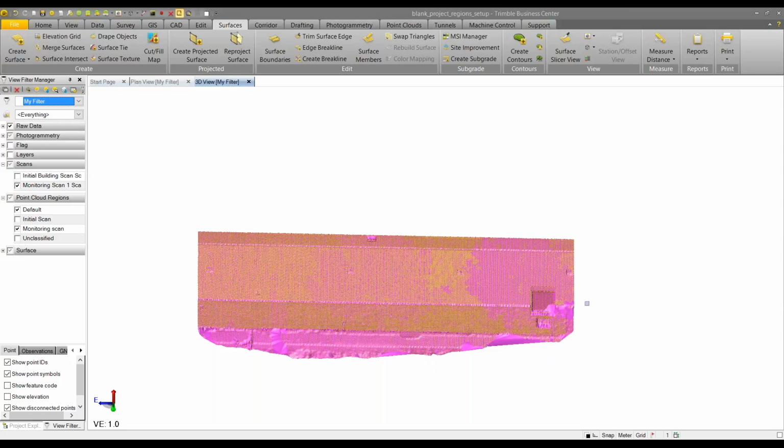So if I've heard you correctly, you're asking if you can use this to monitor cracks or just identify cracks? Yeah. Okay. So you can, but just keep in mind that from the perspective of your plane definition, they may poorly triangulate if they're sort of vertical with respect to that plane definition axis.